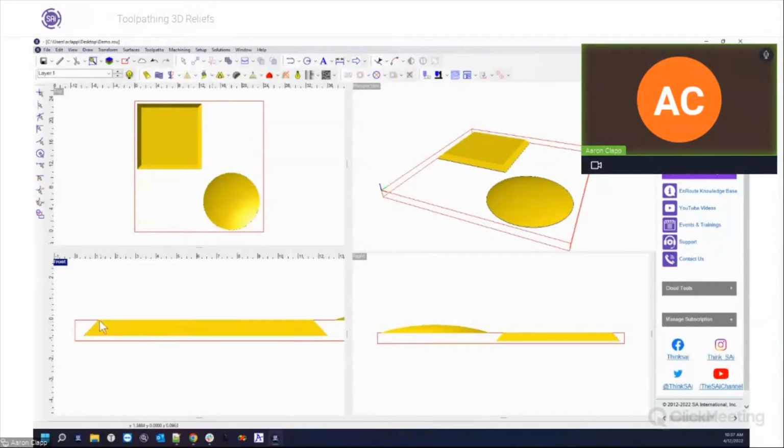Now, something to be aware of is that when I go to cut this, I'm going to have a little bit of a return, or basically a base to it. So I'm going to cut this angled piece, and then I'm going to have 1/4 of an inch of a base to it. If that's okay, great. Then you could just move it to the top of the plate. But if it's important that you not have that base at the bottom and that it be exactly the same size, you're probably going to want to move it to the bottom of the plate and cut off the top.